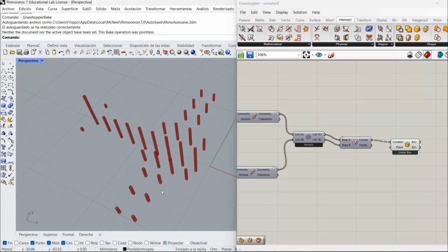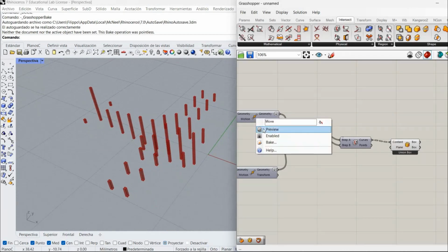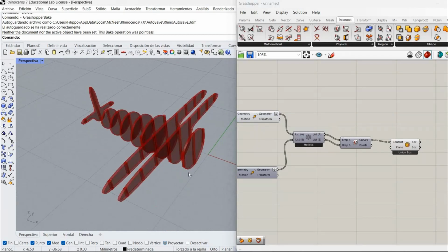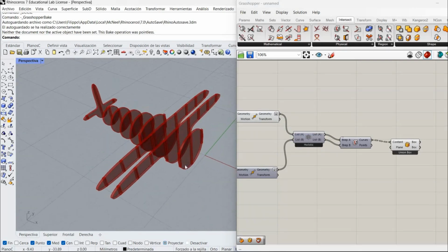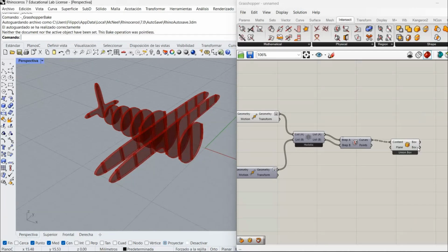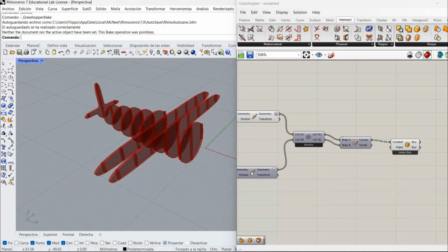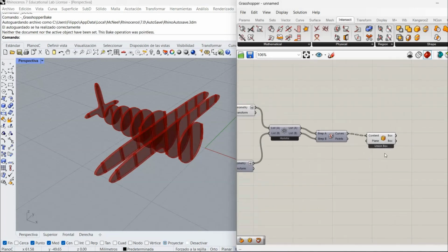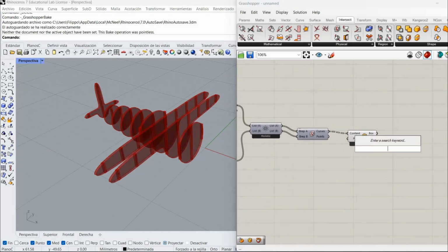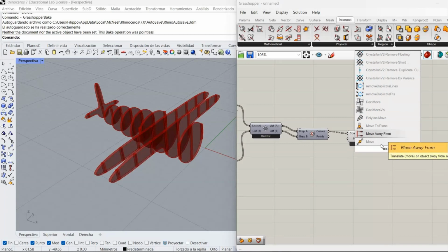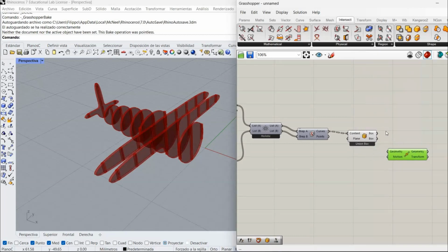For instance, if I turn this on, I want to extract material out of this shape with half of those boxes, because with the other half I'm going to extract the material of the other geometry in the other direction. So to do that, I'm going to move those boxes. Okay, I'm going to come here and move, and I want to move them in the Z direction.